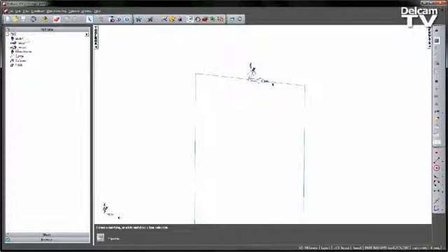However, we can see in the part view we have a setup 1 which is classed as a turning setup. We've also got an additional setup that's being created, and in this case this is a milling setup. So the idea is we can create turning operations and milling operations with their own local coordinate systems.